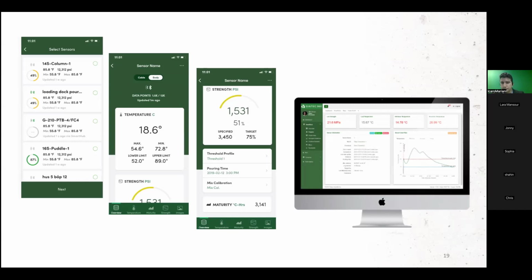How deep into the concrete can it go? Because what I'm getting is you buy all the sensors and they're effectively consumable. You don't ever get them back. How deep in the concrete can it go to have the radio signal still come out? So it depends on what you need. The beauty of the sensors is that they are dual. You're taking a measurement at the tip of this probe and actually inside this logger. This logger must be no more than 2 inches from the surface, because you need the signal. But this cable, you can extend up to 100 feet, depending on how long your element is. Got it. That makes sense. It comes in different lengths. Yeah, right.